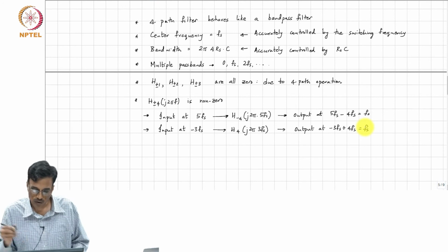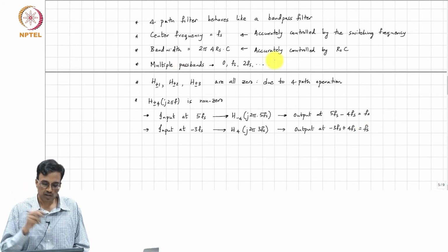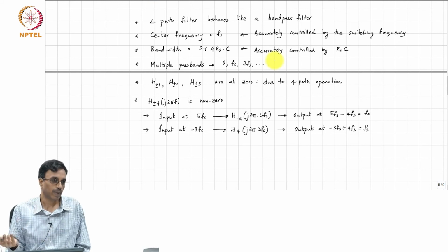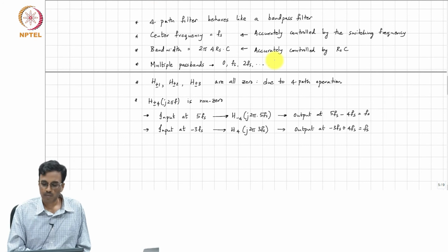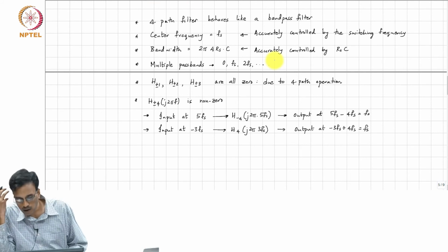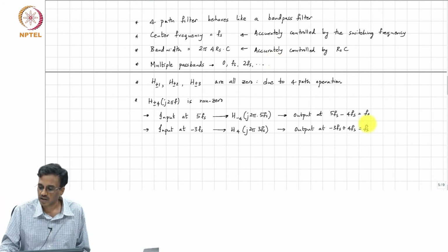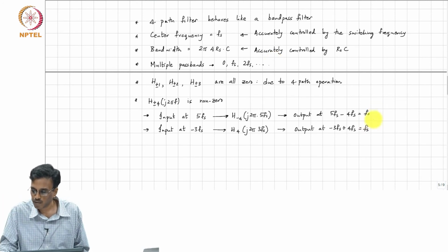right. So, not only are there multiple pass bands, there is also potential for out of band frequencies folding, I mean frequency translation, but we knew this already, right. This is an LPTV network, this is exactly what we signed up for. So, if you want to prevent this, what do you suggest we should do?